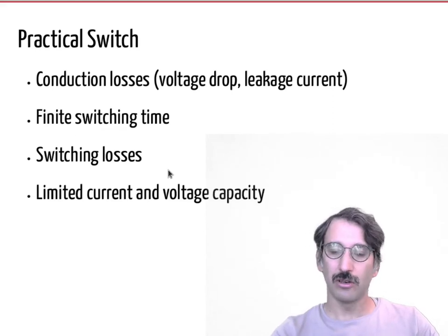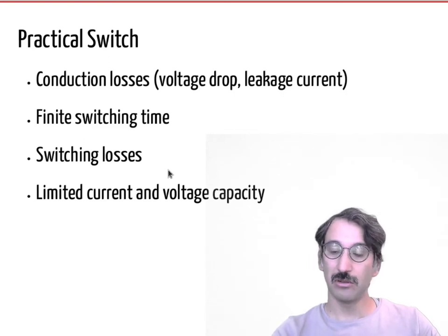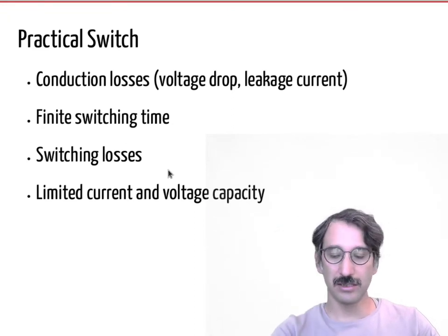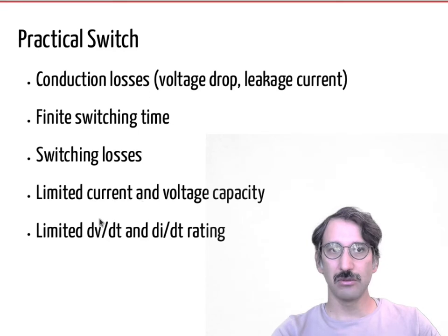And of course any kind of MOSFET devices or transistors have limited current and voltage capacity, so if you go over the defined current limit, you can damage the device. Or even if it is in the off state, if the voltage it is blocking goes over its maximum voltage limit, you can still destroy that device. And apart from that, even if you are not exceeding voltage capacity or current capacity, you can still damage the devices, because they have limited dV/dt and di/dt ratings. So you shouldn't pass those limits which are specified in the data sheets.